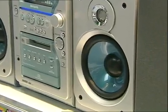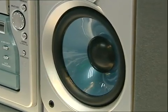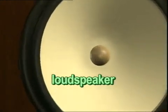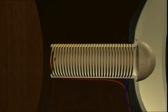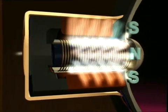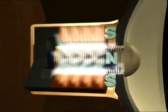A moving coil loudspeaker makes use of the magnetic field of a magnet acting on a solenoid connected to a power supply. It can be gathered from its name that a moving coil loudspeaker has a coil that vibrates freely. The coil is housed in a cylindrical magnet. When an alternating current passes through, the coil is pushed in and out by the action of the magnetic field on the coil, making the cone connected to the coil vibrate and give out sound waves.